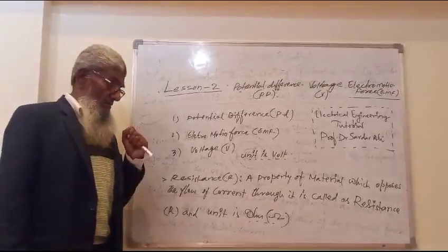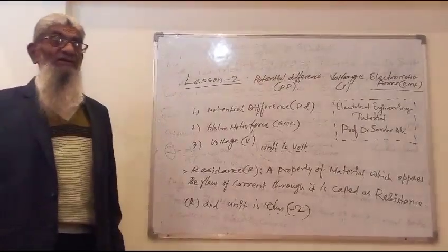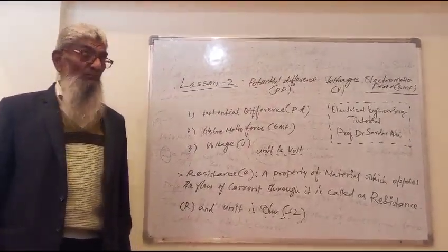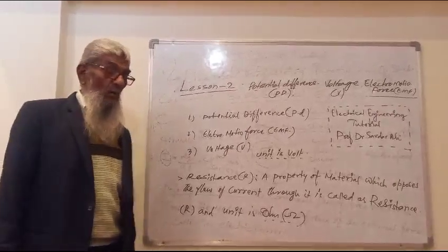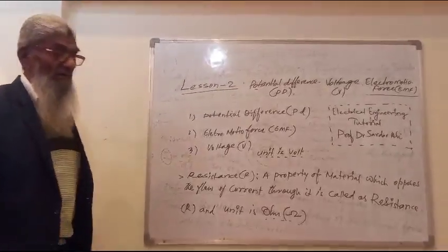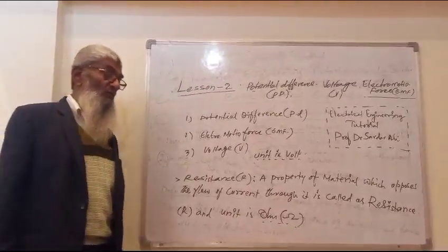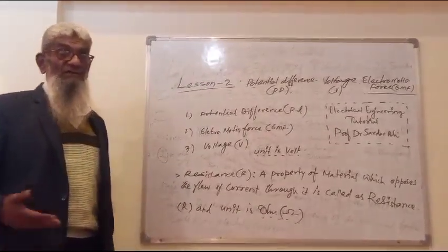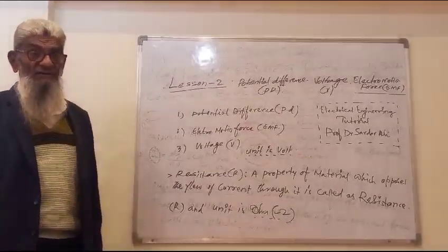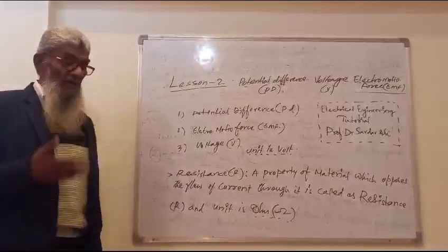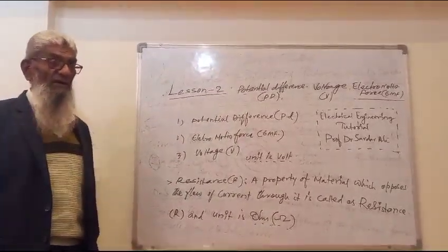Similarly, the higher voltages which are generated in the generating stations are very high. 11,000 volt is the standard generating voltage, that can be amplified to higher values, 33 kV, 66 kV and 110 kV, 220 kV, etc. So these voltages will be transmitted to the substations of the particular area.